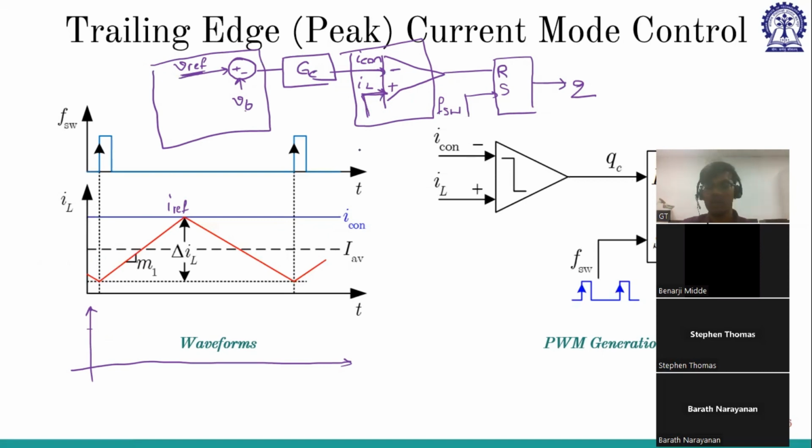The thing I'm confused about is whether the feedback is subtracted or compared. Yeah, it is being compared, because this is the inductor current, right? That's why we compare. Whereas in the case of average mode, actually, he's asking whether IL should be minus. No, this is a comparator. We are not generating the error.